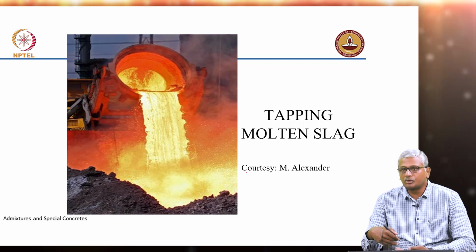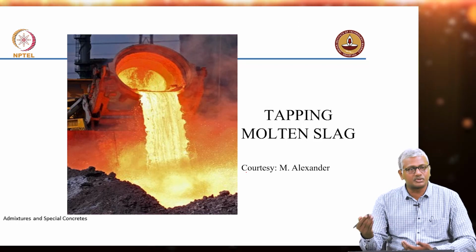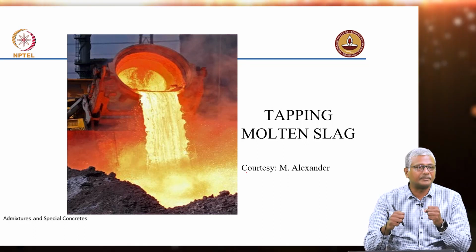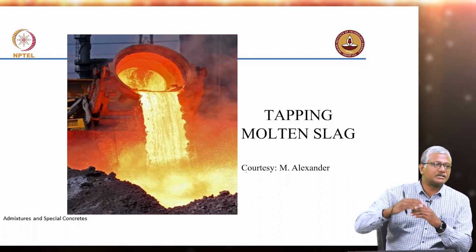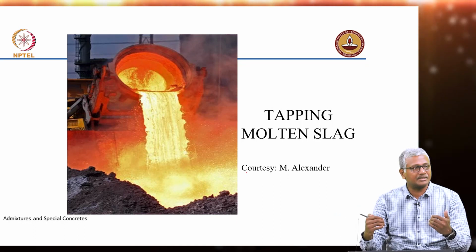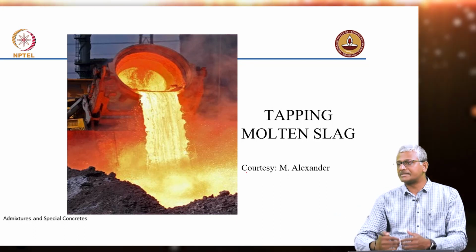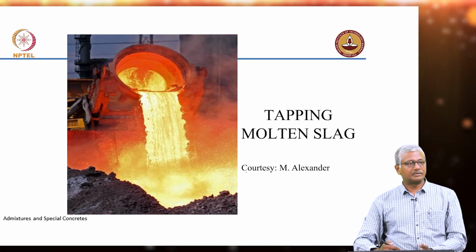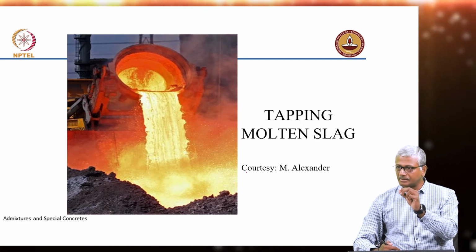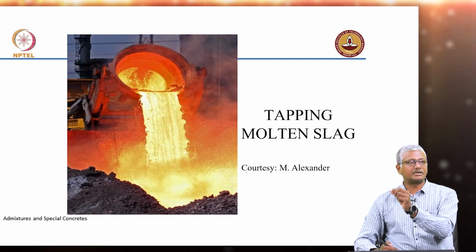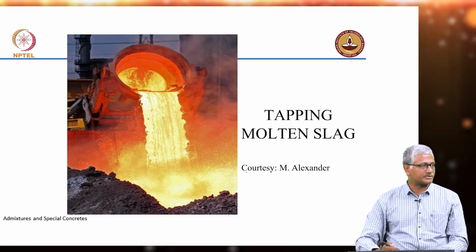Granite is intrusive igneous rock, your basalt is extrusive. All of these are forming from cooling magma. So, extrusive is above the earth's crust or outside the earth's surface, where there is air cooling happening. So, it is relatively faster as compared to the cooling that happens under the earth's crust. So, that is why granite has a crystal size or grain size which is much larger than that of basalt, which is formed on the earth's surface.